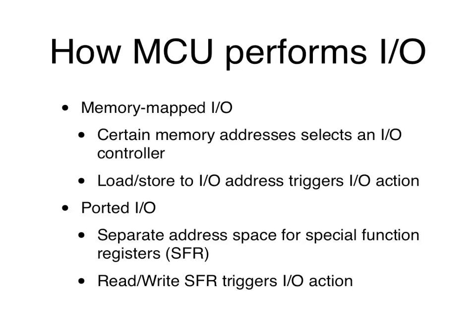Now, ported I/O is a different style. Basically, it uses a different address space for what are called special function registers. This way, you can have a clean separation between input and output actions and your memory access, so your entire memory space is available for actual memory.